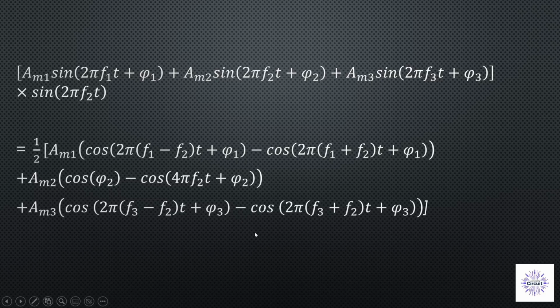So this is the beauty of this method, because as long as our frequencies are not very close to each other, we can use this method to extract our f2 information from the noise or other terms without any issue, right? As I mentioned, this method is sometimes called lock-in.